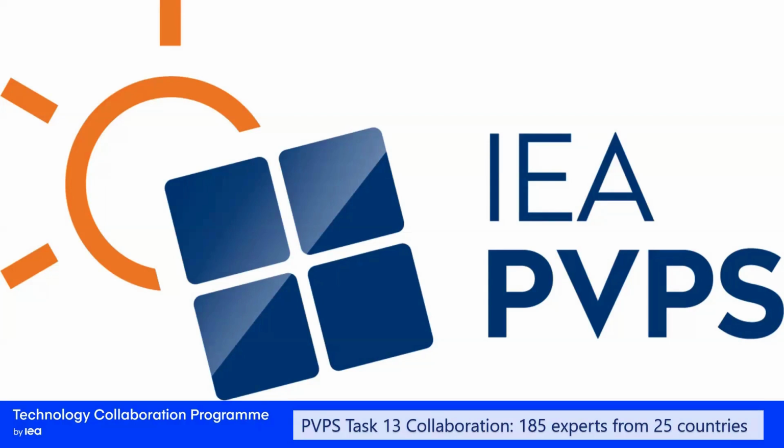There was another part. The other part was, have you considered the effects of spectrum, where the difference in the solar spectrum during clear sky conditions versus diffuse irradiation, and how that might impact PV performance? Yeah, we address that slightly with the simulation, but when it comes to the practical implementation, you also need to have this information. And at the moment, we are only based on the pyranometer sensor, so we have no possibility to address this topic.